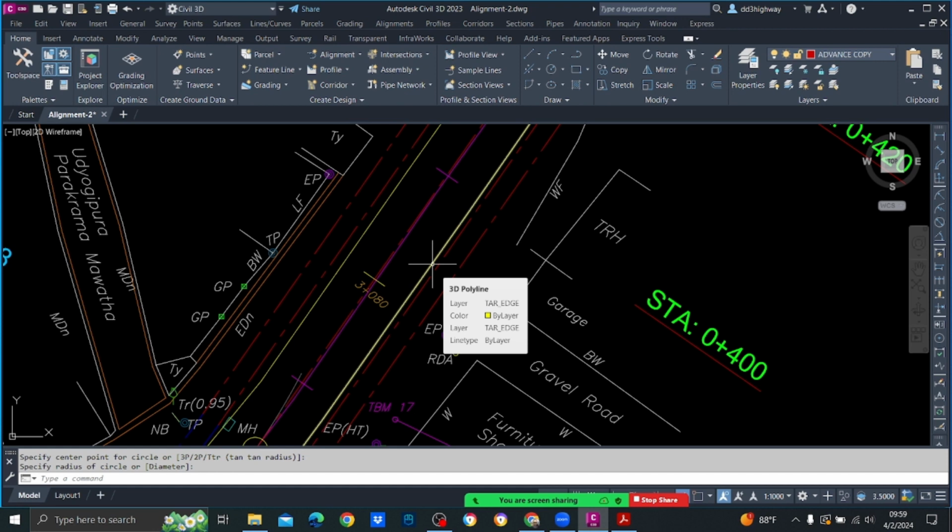Now what I am telling is, our new road is usually wider than the existing road. Now what happens is, if the pavement design is given as the minimum pavement thickness, 100 millimeter should be maintained throughout the existing road. Beyond the existing road, in the widening section, what can be the pavement design?